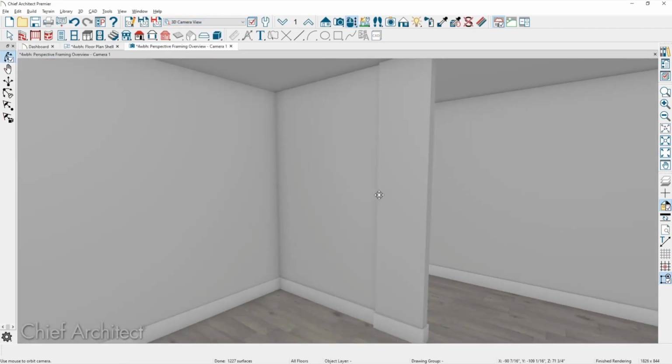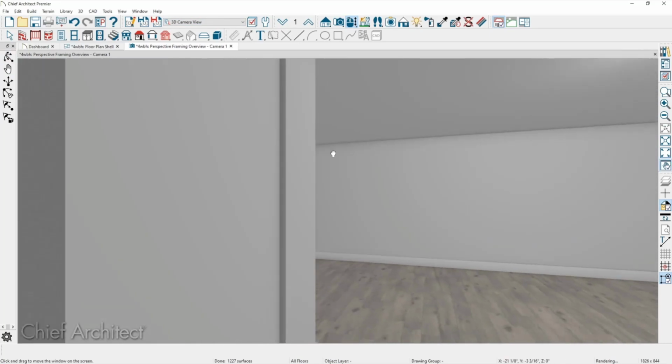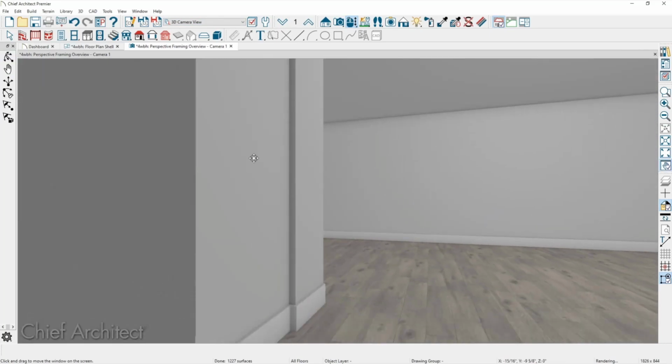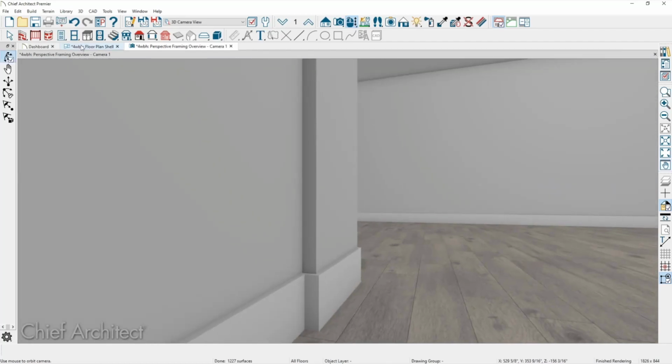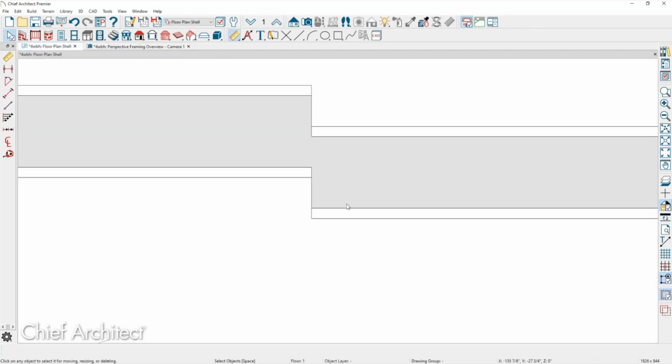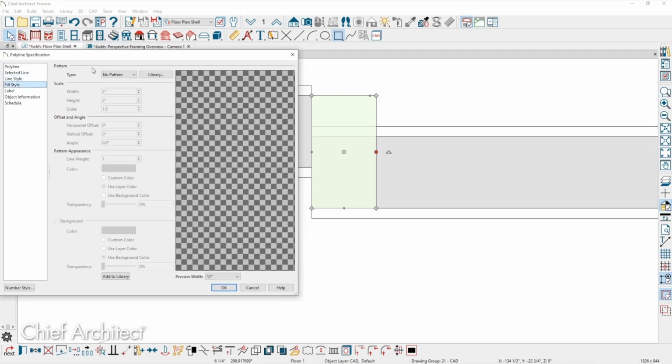And you know, rather than waste a lot of time with it, in the past, I've just used a polyline solid to close that gap and to show the drywall. That actually looks like it hooked up. In that one, it did heal up properly, but it doesn't in plan view. And yeah, that's what I used. Depending on the complexity of the wall, it may not heal at all. Yeah, I just either use CAD or a polyline solid and fill it and move on.